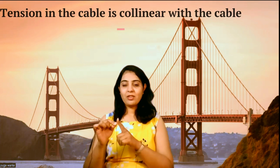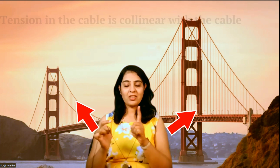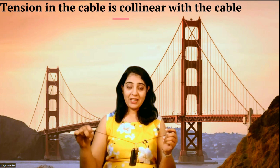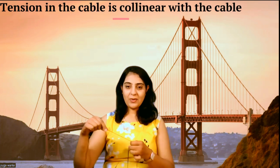We have seen that tension in the cable is collinear with the cable. If there are pin supports at the ends, one vertical and one horizontal component at the cable end will be there, and the resultant will be collinear with the cable.